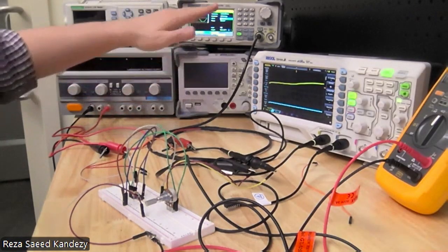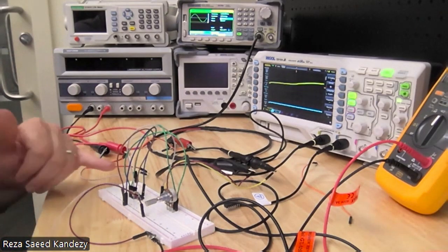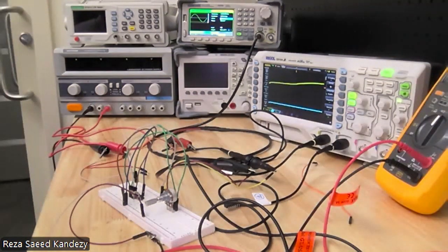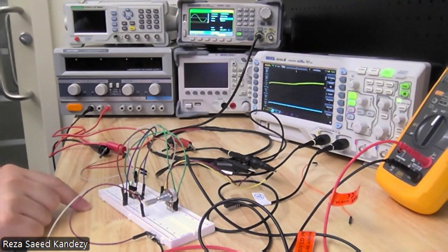Okay, now this is 1 aspect. Another one that I wanted to mention is that we already talked about in the theory part, that the maximum output and actually the range of output that you can get from an op-amp, especially LM324, is from 0, okay, all the way through the VCC minus 1.5 volt. Now, I'm expecting somewhere between 800 millivolt all the way to 8 volt.